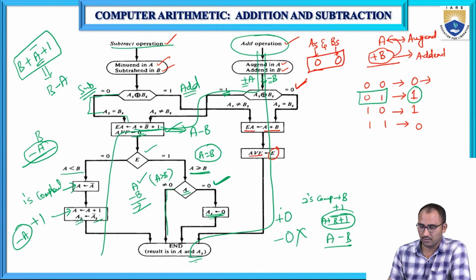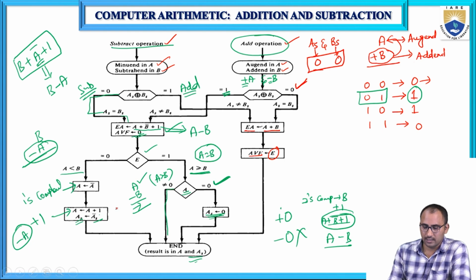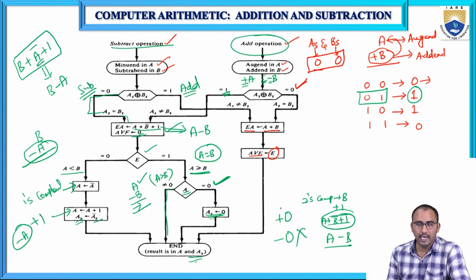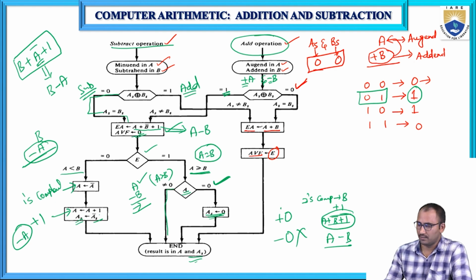Coming to the subtraction, when the signs are same, we will perform subtraction. When signs are different, we will perform addition. Okay, so this is the hardware algorithm to perform the addition and subtraction.